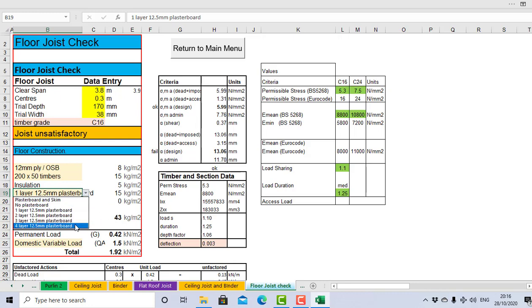That reduct flooring system might have 2 layers of plasterboard, and it may have a layer underneath the timber decking, and it'll tell you in the instructions what the weight is. Say for argument's sake it's 15, you would stick it in there and it would pick it all up. But we won't do any of that malarkey. We'll just keep it at 1 layer of plasterboard, and we'll pop that back up to 22mm chipboard.